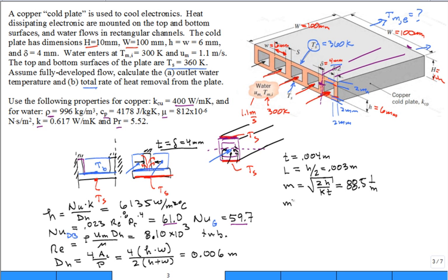All right. Now, the product mL is usually computed, and then we take a look at it. The mL is 0.2656, and it's dimensionless. If you want the efficiency of the fin, for the single fin, it's the hyperbolic tangent of mL divided by mL, and that gives us an efficiency of a whopping 97.7%. It's as if that fin is isothermal. There's a small temperature variation throughout the fin.